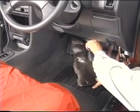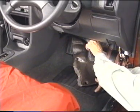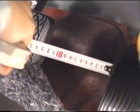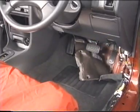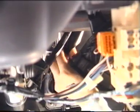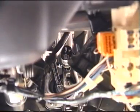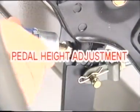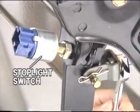Remove the floor carpet under the pedal and measure the distance between the asphalt sheet and the surface of the pedal. In this case, the pedal must be adjusted. Remove the wire connector from the stoplight switch. Loosen the lock nut of the stoplight switch and turn the switch itself 2 or 3 times to loosen it.